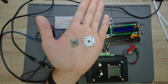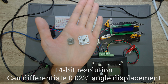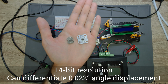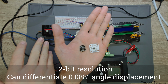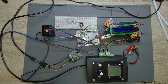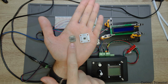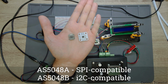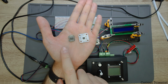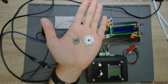magnetic position encoder. The main difference between these two is that this one is 14-bit resolution, and this one is 12-bit resolution. For those of us working with, for example, stepper motors, it doesn't really matter, because these two resolutions are quite huge anyway. But this one, with the A at the end of its name, has an SPI connection. You can see these solder tabs here, and actually those are the SPI pins.